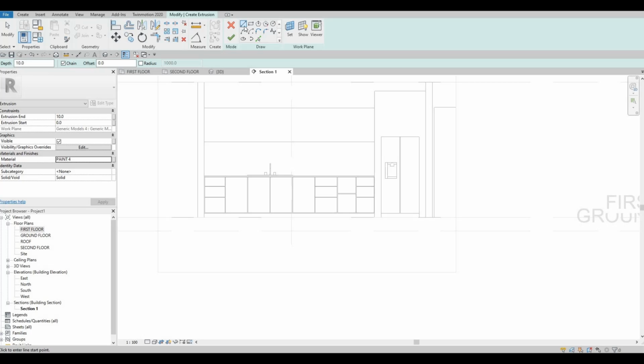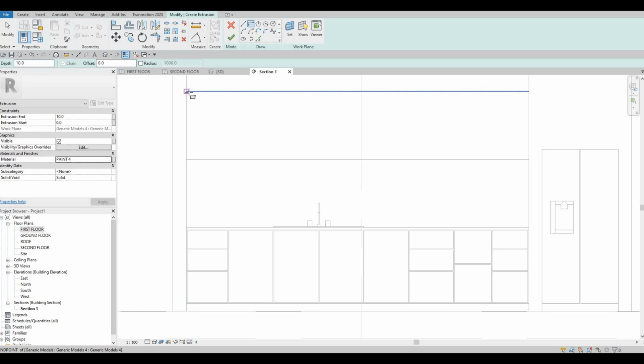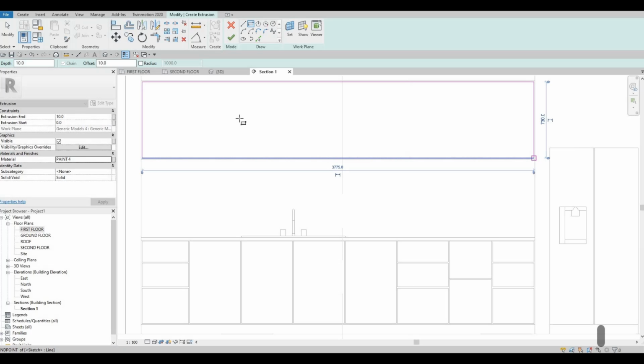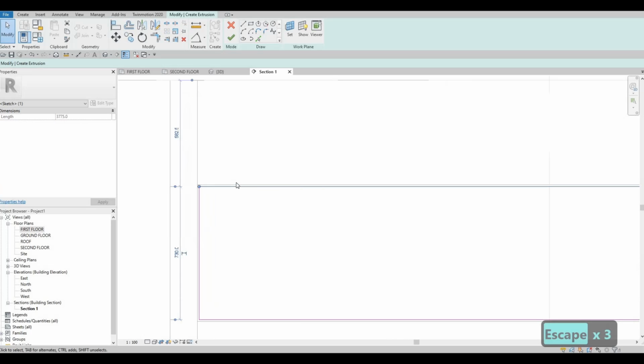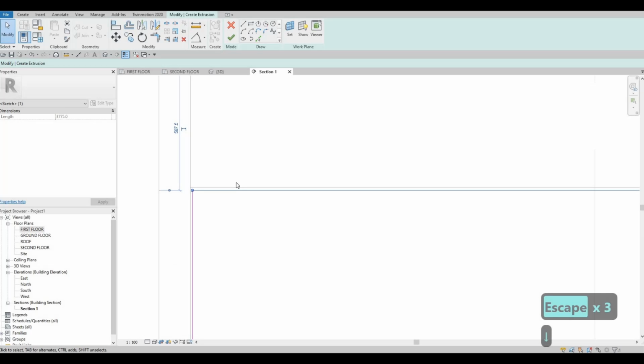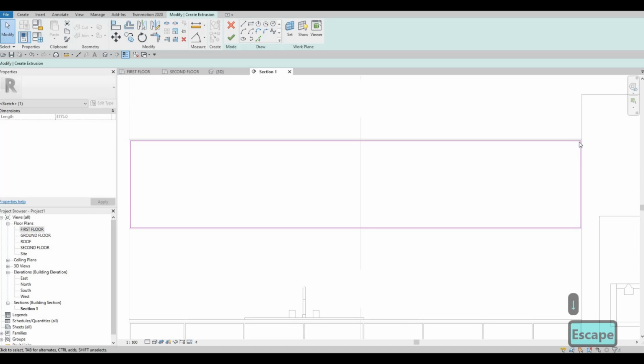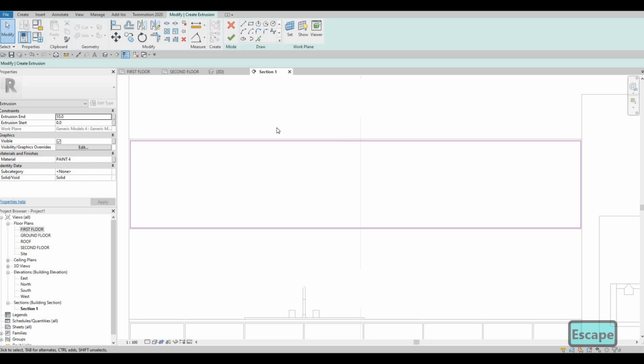And now click on rectangle. And then here, what we're going to do is offset this to 10, and then from the inside again. So space bar, and then select it there. Here, we're going to select this one, and then just nudge it one more so that we have more space at the top there.